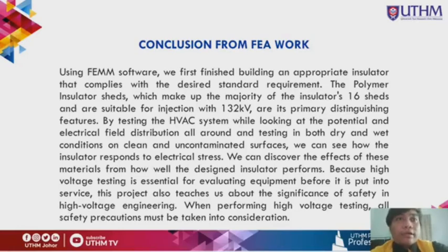So I will continue to the conclusion from the FEA work. In the conclusion, we are able to successfully simulate the distribution of high voltage and electric field from the insulator tested by this group using the result from the finite element method, FEMM.